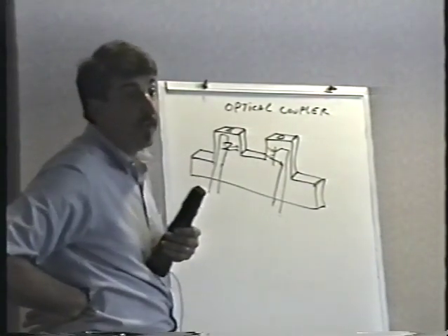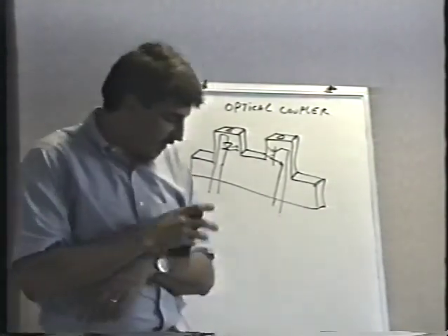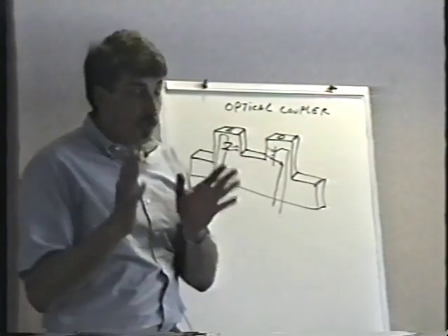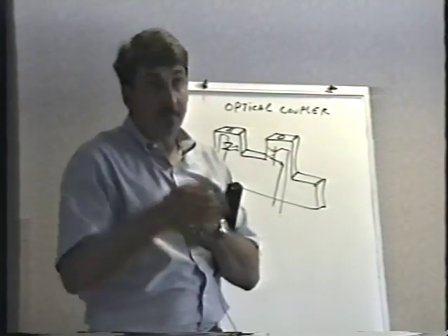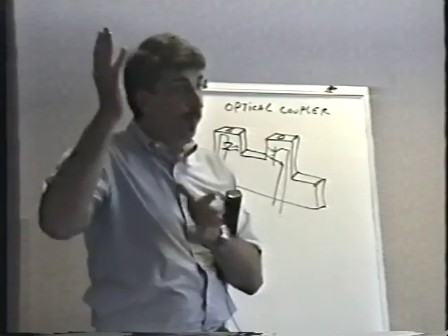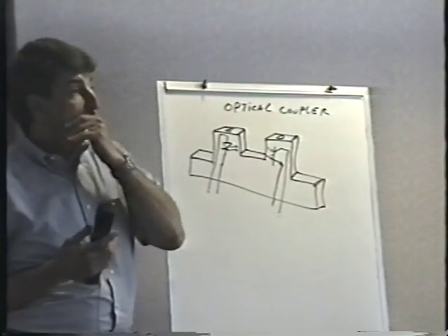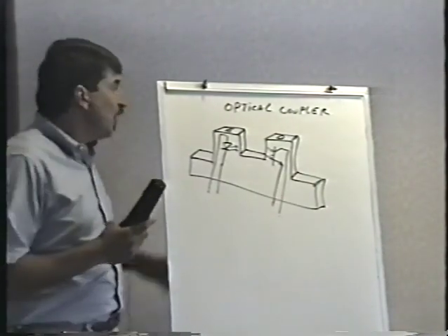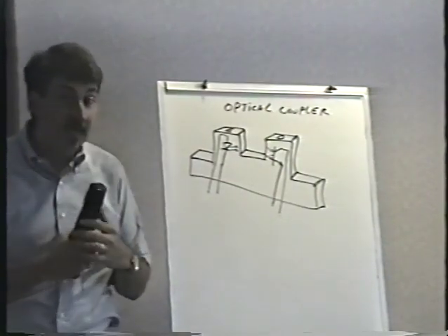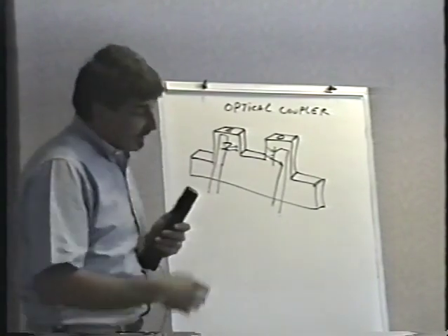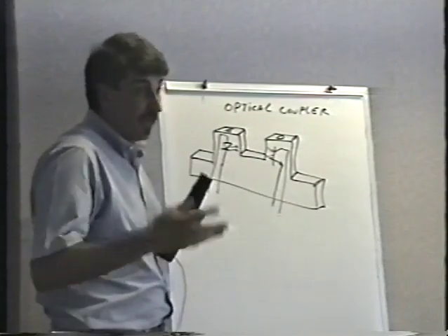So to be honest with you, what we do is substitution. In a trackball assembly, it's easy, because you have 2 optical couplers. One is for up and down, one's for left and right. If it's not moving left and right but is moving up and down, and you swap the two and the problem moves to the other direction, then obviously the optical coupler is bad. On the other hand, when there's just one optical coupler, like a steering wheel, if it doesn't steer, quite honestly, I change the optical coupler and that usually fixes it. Of course, don't forget to clean it first. A lot of times it's just dust and dirt.